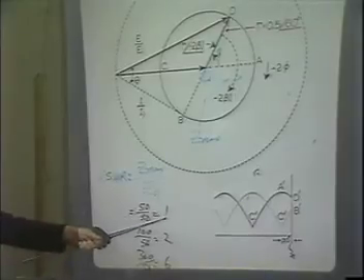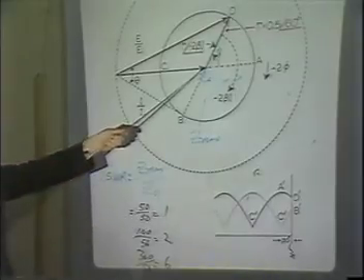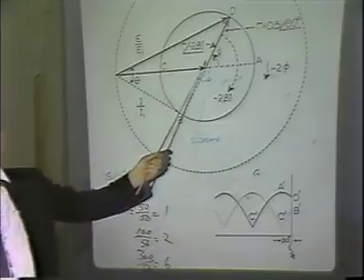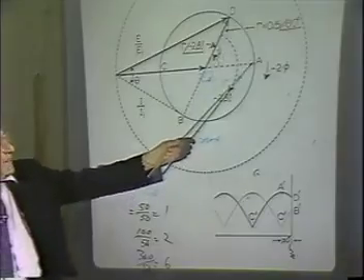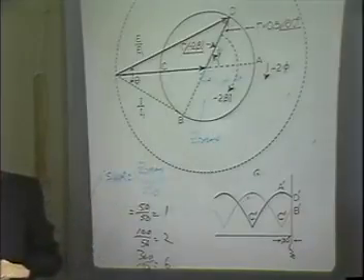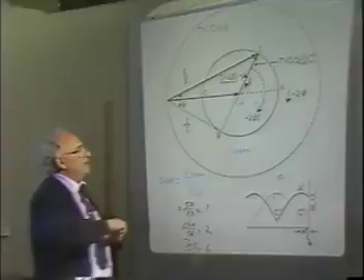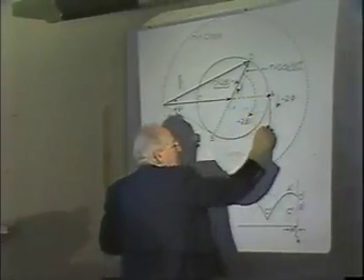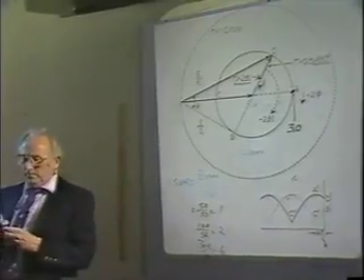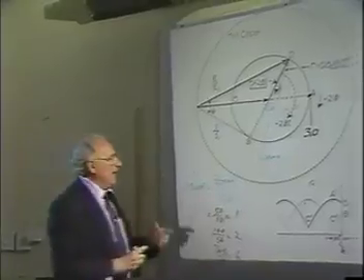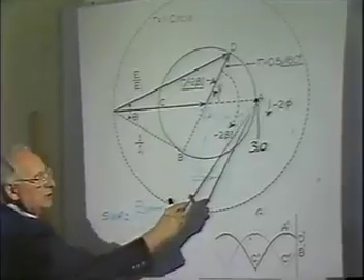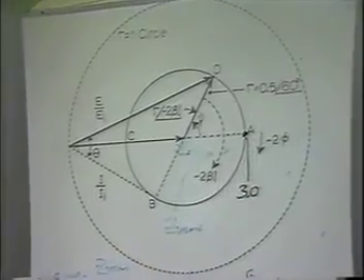One, where is this located? Right here. 1.0. Where's the 2? Out here, isn't it? Halfway out here is 0.5. What is the VSWR for 0.5? You looked it up before? Don't ever forget that. It's 3 to 1, right? That's a voltage standing wave ratio of 3.0. Right? What's going to happen then is you go out here to 300 ohms. That was 150 ohms, wasn't it? And you go out to 300 ohms, so it'll go 3, 4, 5, 6, on out to infinity, won't it?